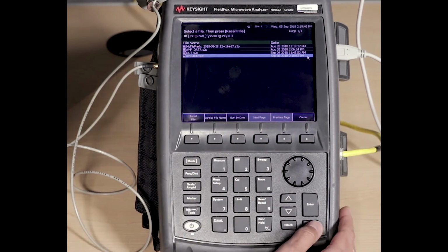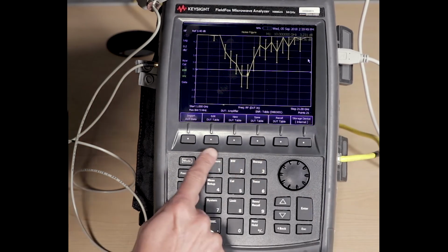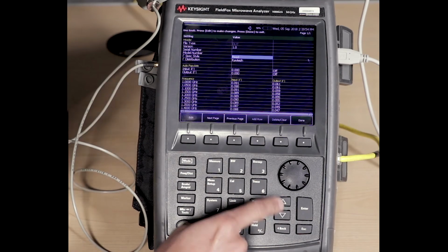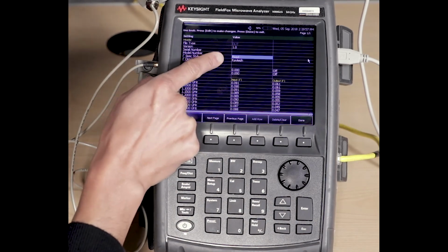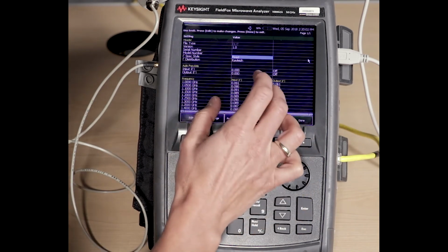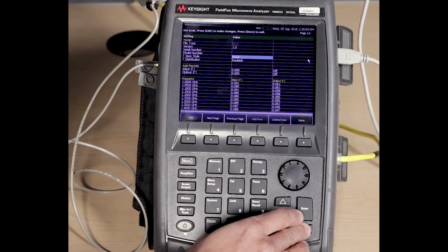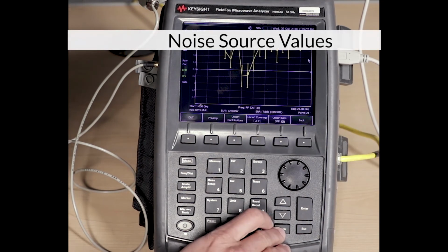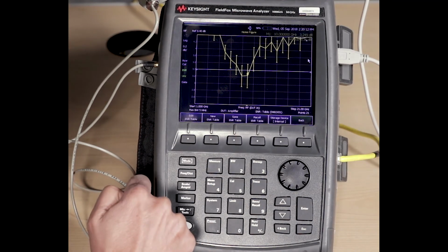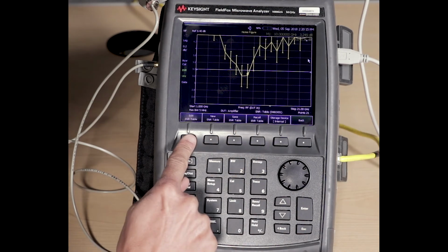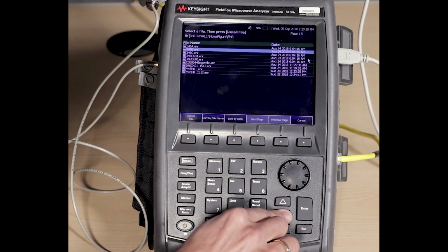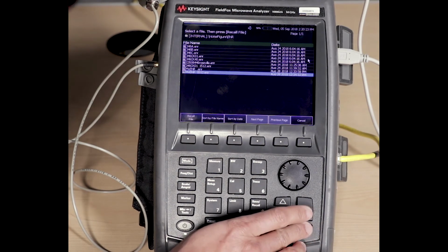This is also true for ENR values. So you now have your DUT values, and again, the distributions I had selected in the spreadsheet, the fixed and the Rayleigh, you want to have those here. It's really important that these are right for your uncertainty to be right. And you do the same thing for the noise source. You do mesh setup, noise source, edit recall tables. I can save a CSV on my computer, and then I can recall the CSV here, like my ENR file. The ENR format is a CSV format.